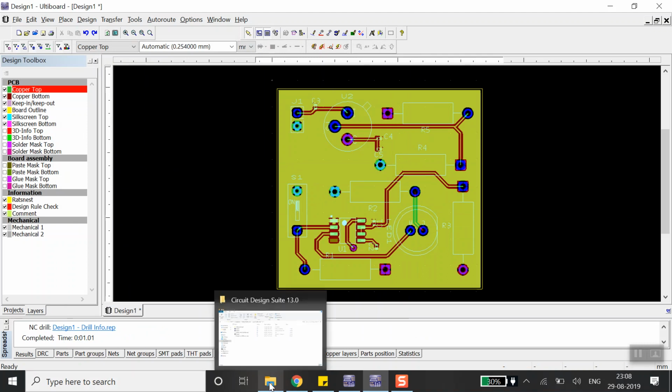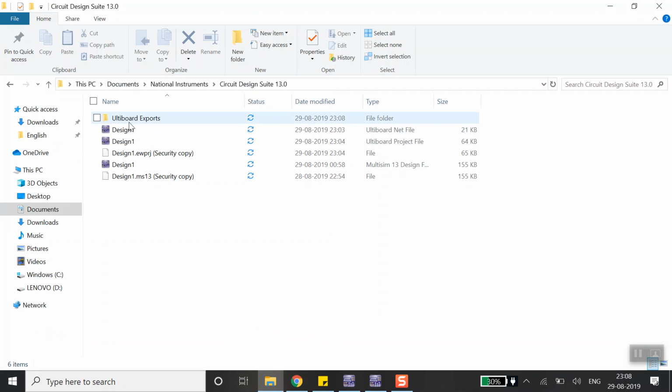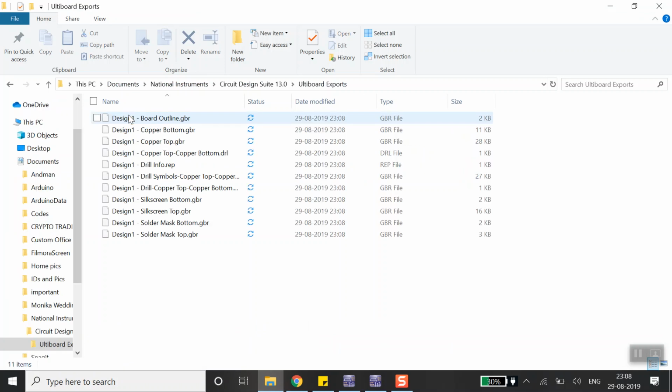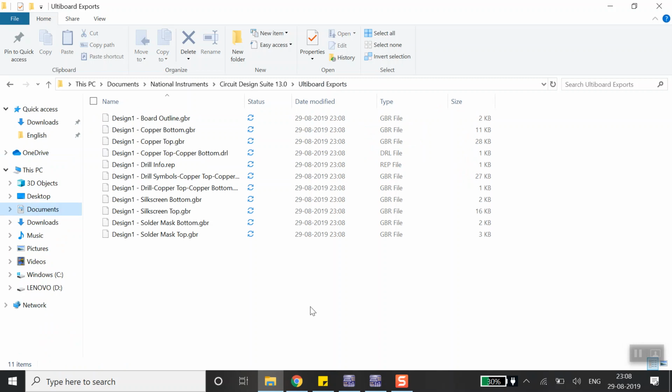Where you saved the file, you will see that a new folder has been created, named Ultiboard exports. Over here you will see all the GBR files, and that's what you have to give to your manufacturer, and he will provide you with a fresh new PCB.